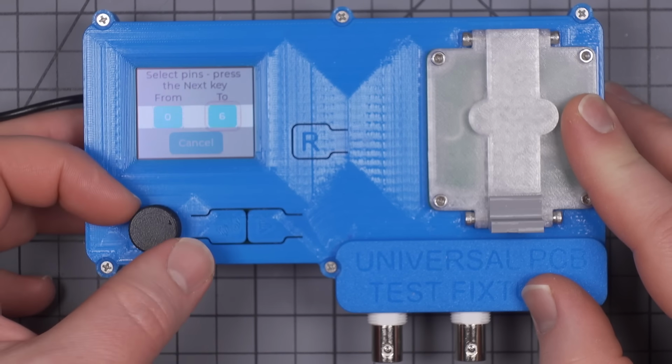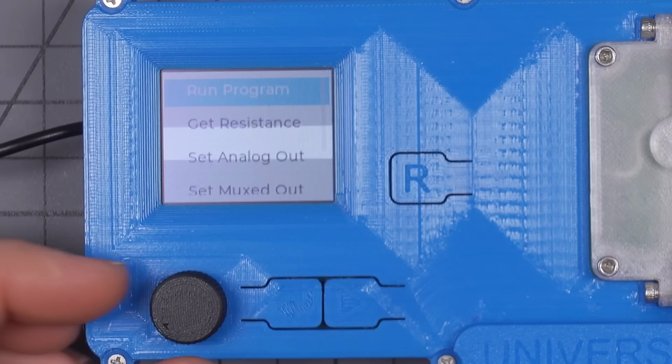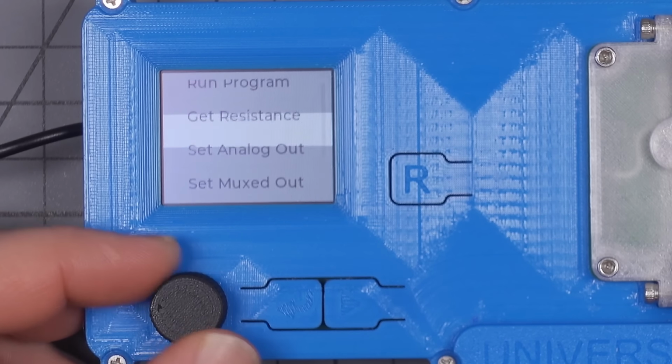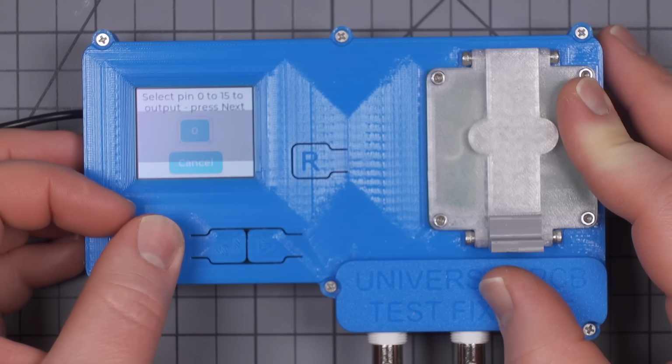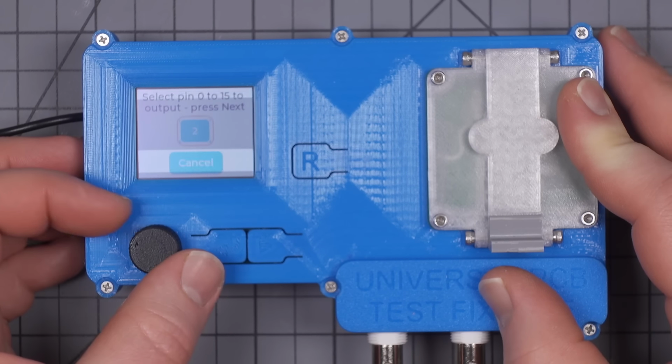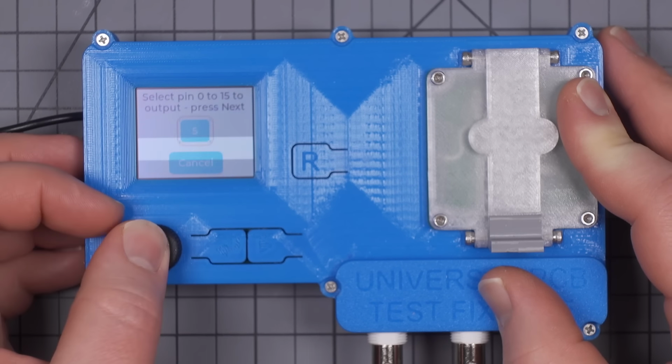The way I do this is to have a variable keep track of my position on the screen, changing it in response to the up and down signals. When OK is pressed, simply call the appropriate function based on the current cursor location. A caret or highlighting a line works great to indicate your location. Encoders and buttons are also great for changing values on screen, say to input a number. For all these cases, you'll need logic in the background that updates the display based on your inputs.